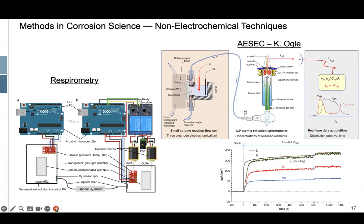Another technique we will be talking about is respirometry, which was originally developed in the chair of surface science and corrosion at FAU. It can monitor the oxygen reduction reaction and the hydrogen evolution reaction, which are the main cathodic reactions that happen during corrosion. We can use respirometry to monitor in real time how much hydrogen is evolving or how much oxygen is consumed during the reaction.